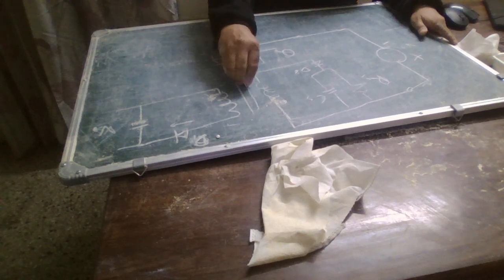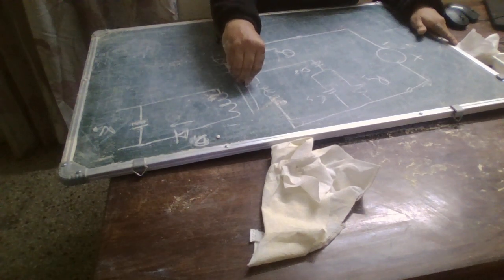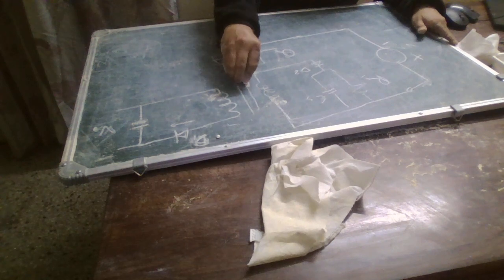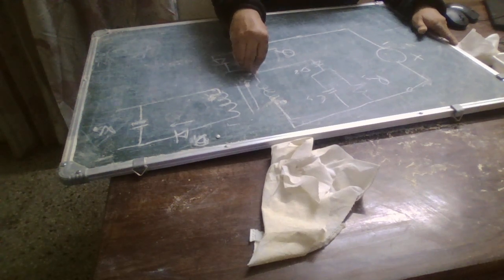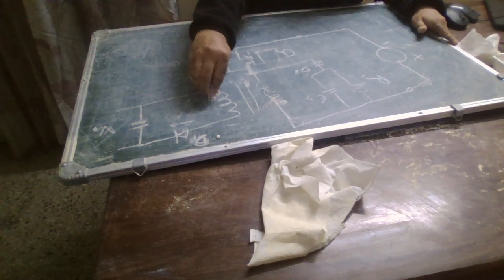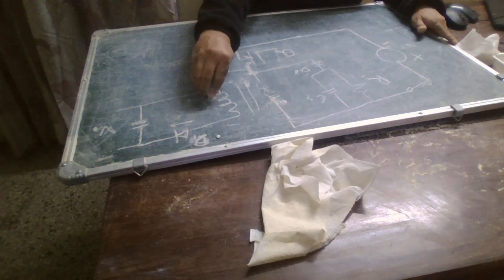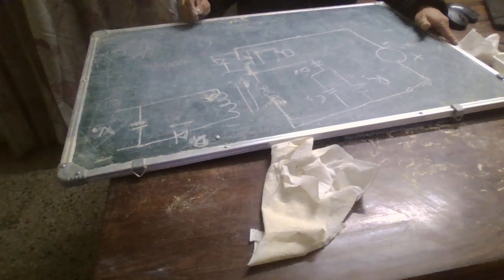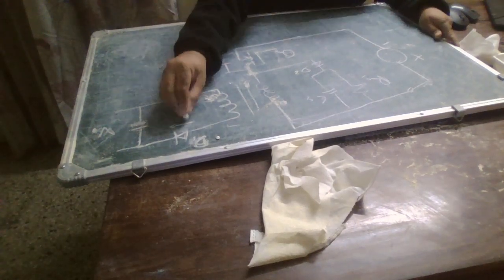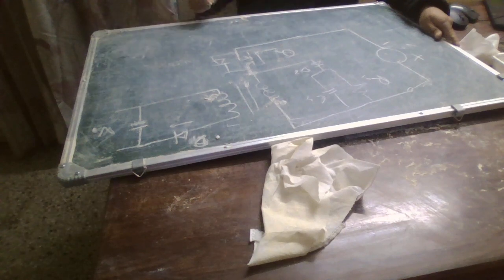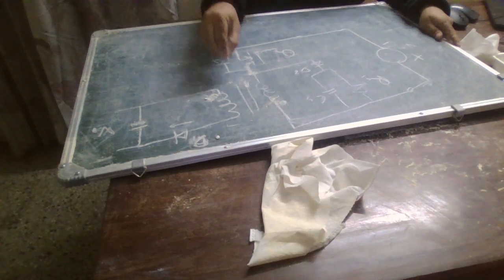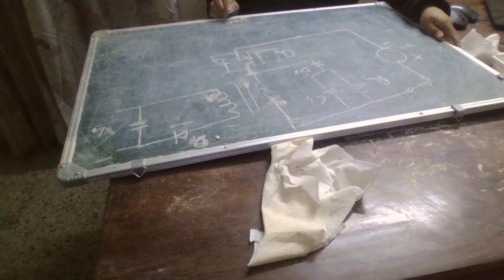Since the transformer is behaving as an inductor, it has an inductance property. It cannot instantaneously change the magnetizing current value. Rather, the dot end now induces a negative voltage. As a result of this, the diode becomes forward biased, and it completes the circuit path. The stored energy which is in the inductor is given to the load.